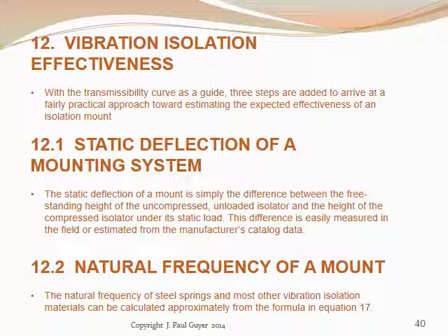An uncompressed 6-inch high steel spring that has a compressed height of only 4 inches when installed under a fan or pump is said to have a static deflection of 2 inches. Static deflection data are usually given in the catalogs of the isolator manufacturers or distributors. The data may be given in the form of stiffness values.